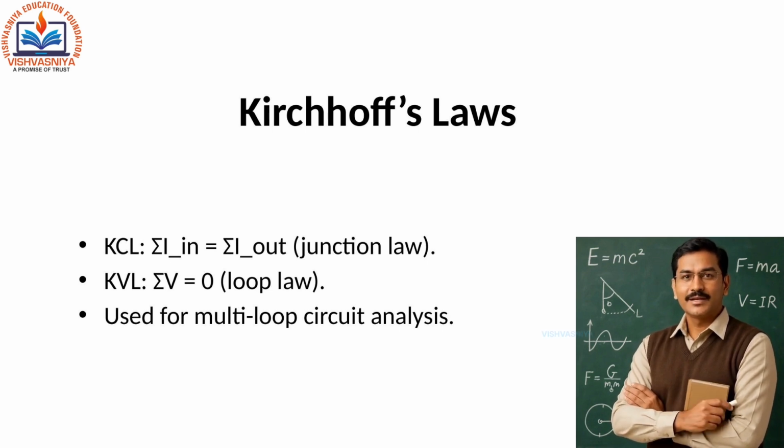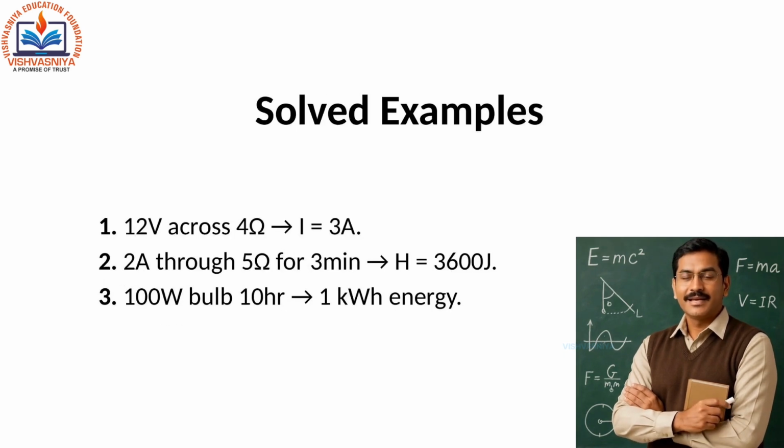Kirchhoff's voltage law, KVL, says the algebraic sum of all potential differences in a closed loop equals 0. Sigma V is equal to 0. These laws are extremely useful for solving multiloop circuits. Let's look at some simple examples to apply these concepts.